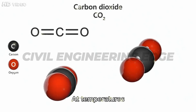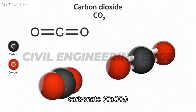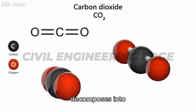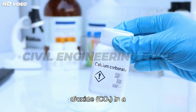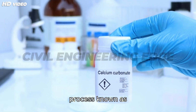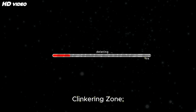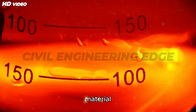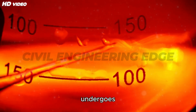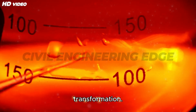At temperatures around 850 degrees Celsius to 1000 degrees Celsius, calcium carbonate (CaCO3) decomposes into calcium oxide (CaO) and releases carbon dioxide (CO2) in a process known as calcination. 3. Clinkering zone. At 1400 degrees Celsius to 1450 degrees Celsius, the material undergoes partial fusion and chemical transformation.